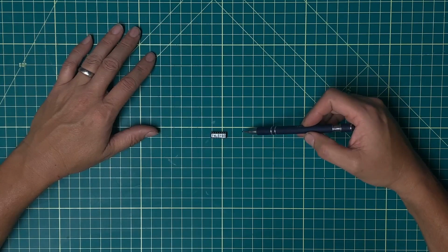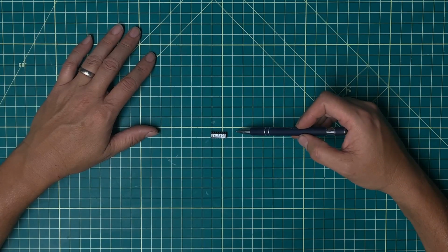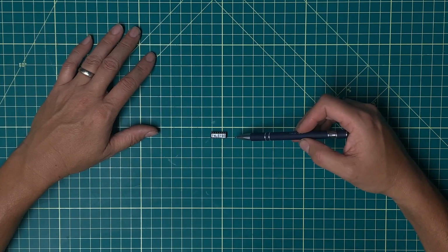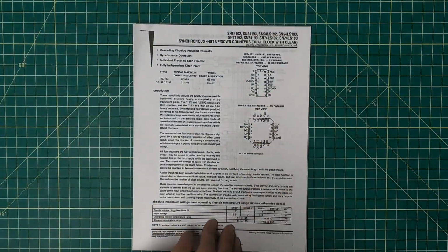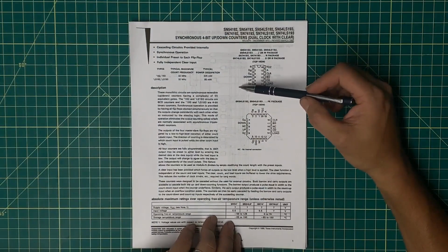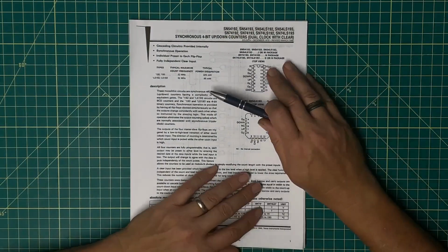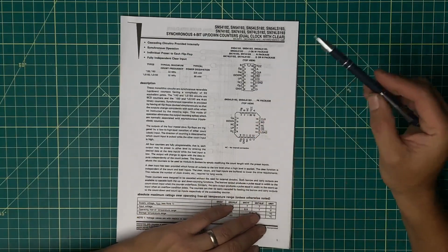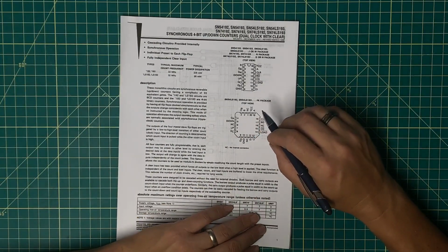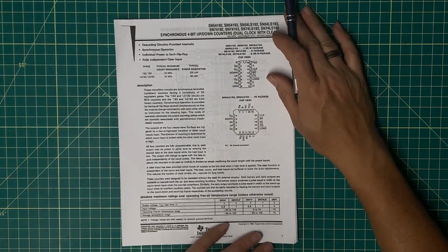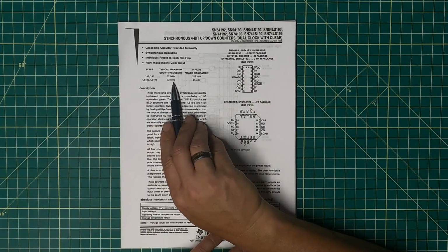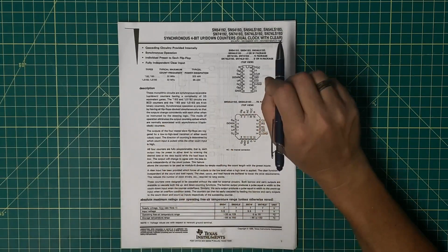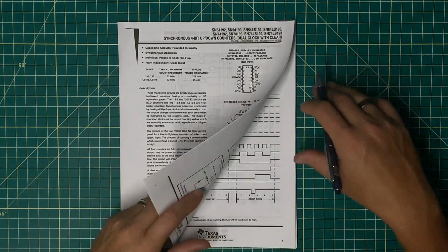Okay, let's start by taking a good look at the 74LS193 IC that I started with. Now this is what I built my prototype on the breadboard with. Now I've pulled out the specs and printed them out because I want to be able to do some calculations off to the side. Unfortunately, I've got some math to do, so bear with me a little bit. But the specs here say that the LS193 should be able to operate at a maximum count frequency of 32 megahertz. Seems quite reasonable, actually.